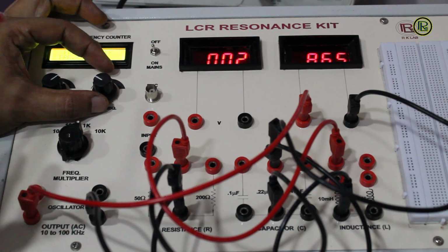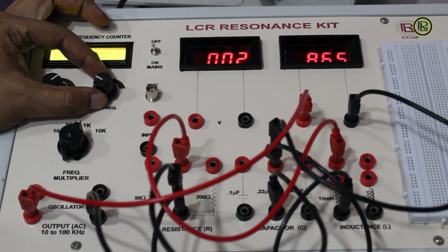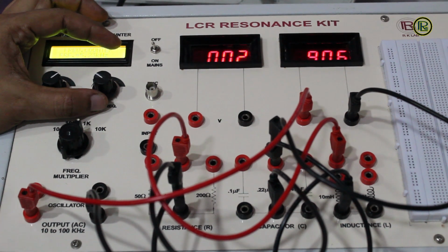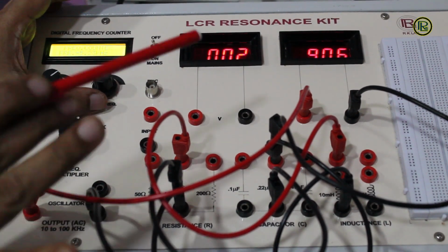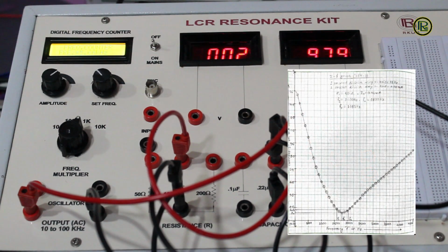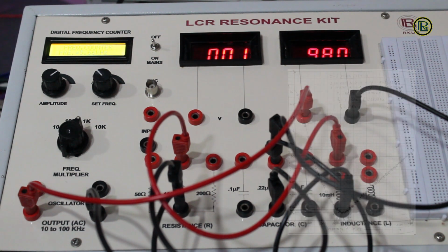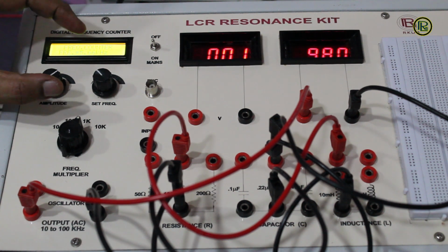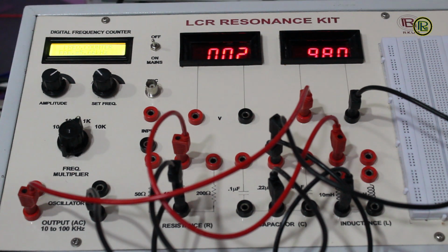So I have crossed the anti-resonance frequency, and the feature I showed you in my slide, now we are able to find it happening here. So if I plot the current with respect to omega along the x-axis, then we will be able to get the anti-resonance curve, and from the response curve we will be able to find out the quality factor as I discussed in the slide. One thing I want to mention here is that each time I change the frequency, the amplitude should remain constant. We have to monitor it in some way.